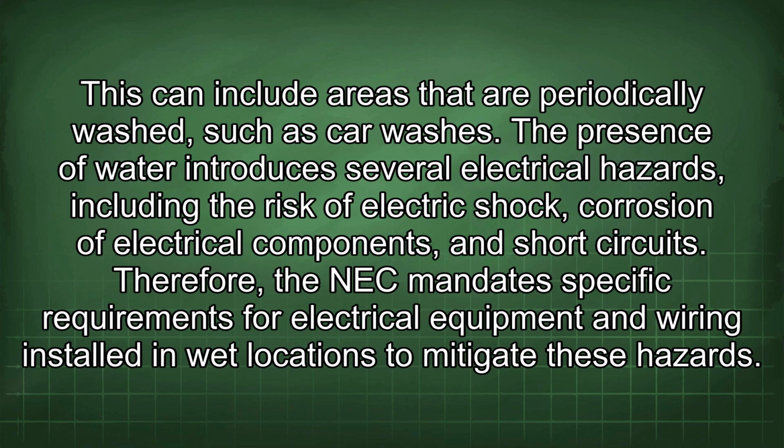The presence of water introduces several electrical hazards, including the risk of electric shock, corrosion of electrical components, and short circuits. Therefore, the NEC mandates specific requirements for electrical equipment and wiring installed in wet locations to mitigate these hazards.